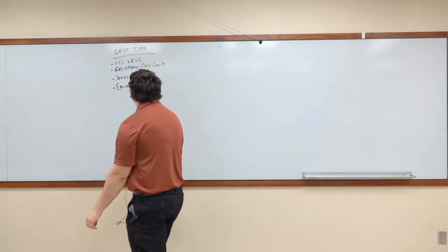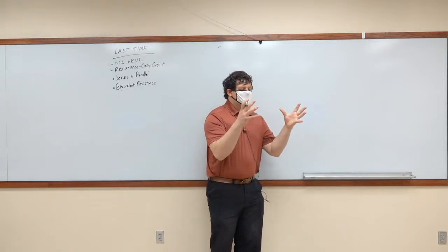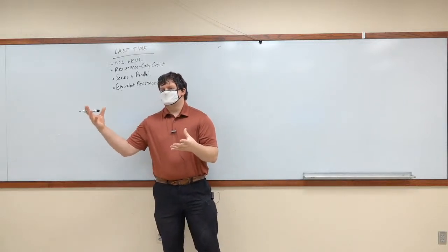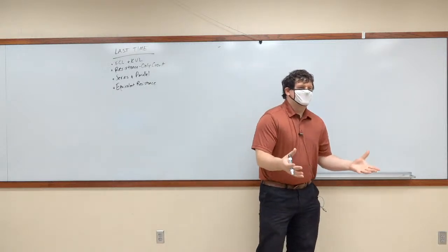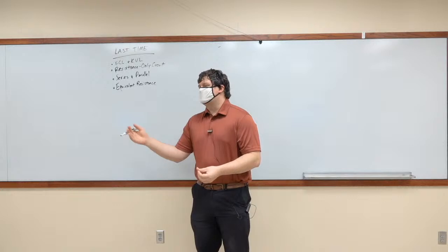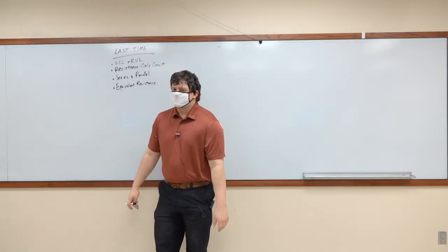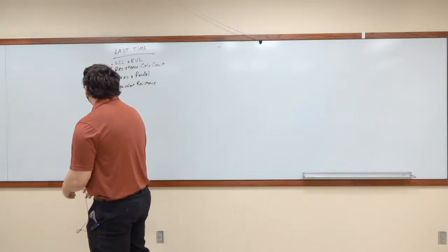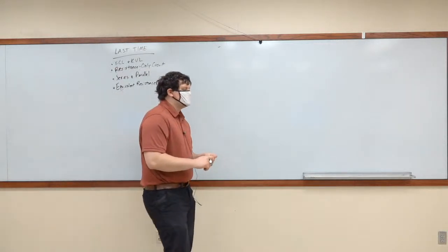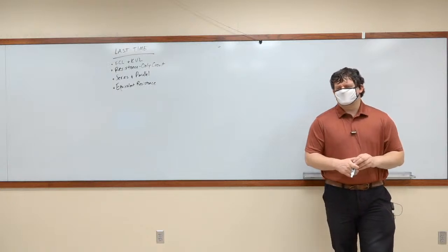Okay, we're going to keep going. So with equivalent resistance, the concept is that you can take a bunch of resistors and combine them and find one resistor that has the same behavior as a bunch of resistors. If you only have a 100 kilo ohm resistor and a 50 kilo ohm resistor, you can turn them into a 150 kilo ohm resistor instead of having to buy a 150 kilo ohm resistor, that kind of thing. Or if you're looking at impedances, you can add them all together. This is kind of a principle that we're going to look at a lot as we build into this course.